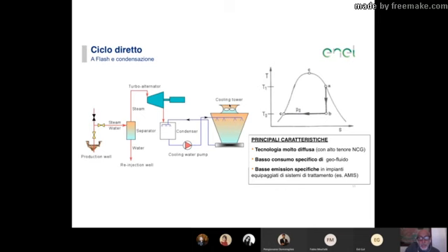So into the emissions. In addition, they can also add ammonia, if there is too much SO2, then they add ammonia into it. Or if there is too much ammonia in the geothermal fluid, they add sulfuric acid to produce ammonium sulfate, which is very soluble, and then can remain in solution in your condensed water.